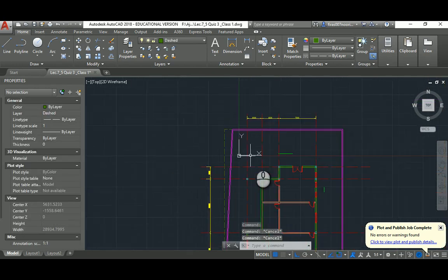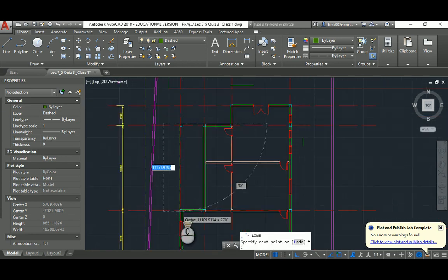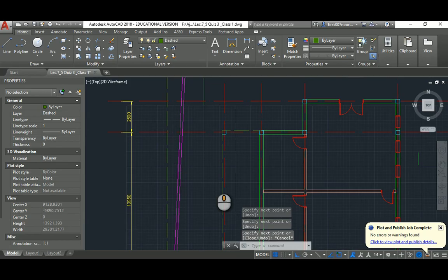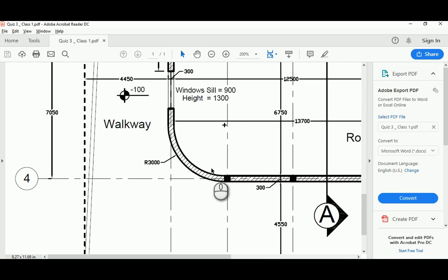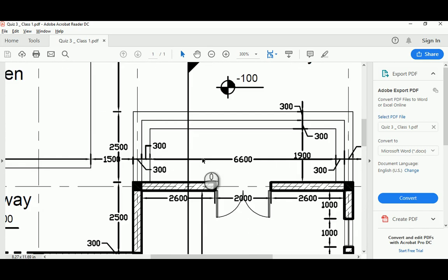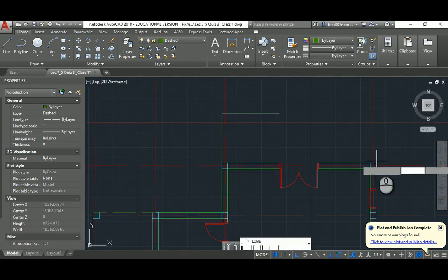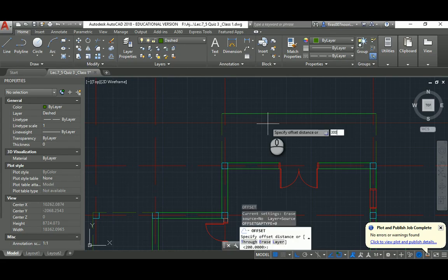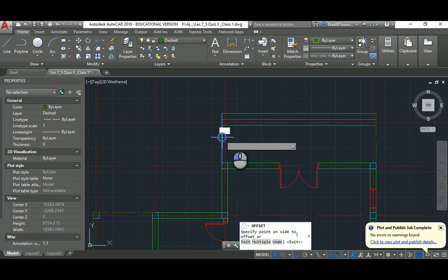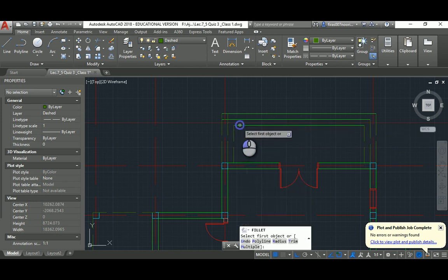Nice and easy. Now we have that correct. I'm gonna have a line here and then a line here for this. Beautiful. So now we have this guy and we have this guy again. You can change the line type scale for it if you like it, but it's okay with me. Now those guys, beautiful. So you're just gonna connect this and this. I know it's the wrong layer, it's okay, forgive me with this. And it's a 300 offset, so 3 1 2 1 2, same thing. And then fillet those guys, multiple fillet. A new layer.